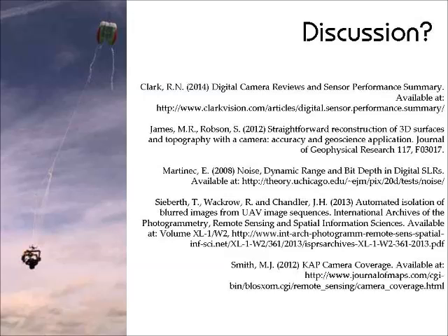In terms of motion blur, you've got some competing effects here. Pixel size, flying height, focal length, shutter speed. Perhaps the simplest thing to change here is your flying speed. If you go slower, you're going to get less motion blur. So hopefully you've got a greater awareness of the impact of your camera